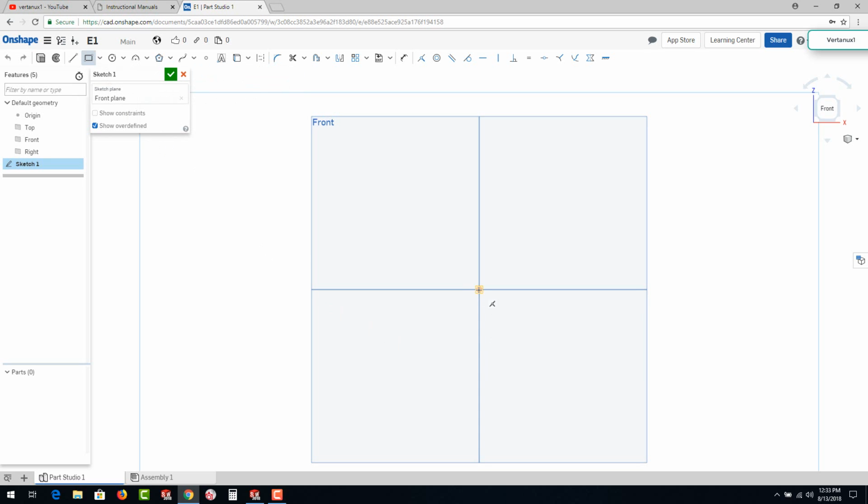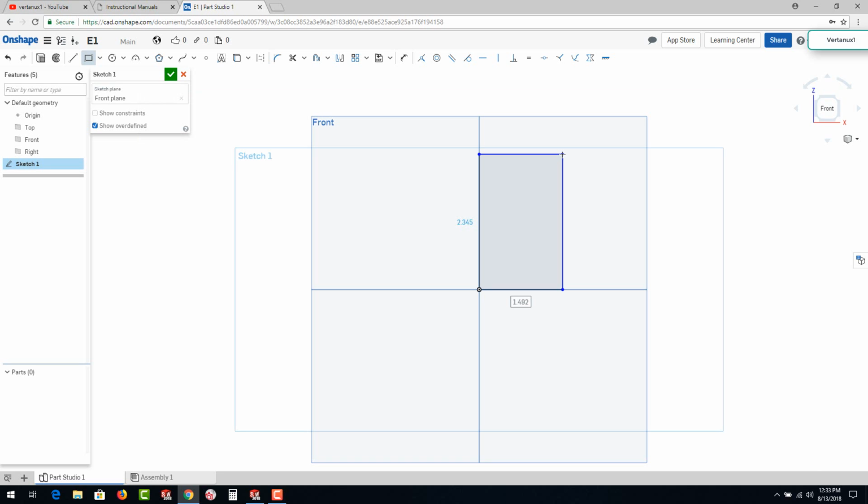I'm going to glide up to this point, and I'm going to click and drag this out. You can see the numbers come up for the approximate dimensions, and you could use those. As you click here, you'll see it will highlight one of them. It actually has a little box over it, and you could go ahead and, oops, I meant to actually type in the value there. I accidentally clicked on it, so I lost it, but that's okay, because we need to learn how to use the dimension tool. And right up here is the dimension tool.